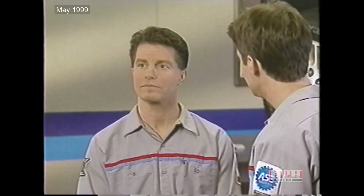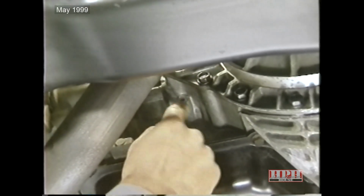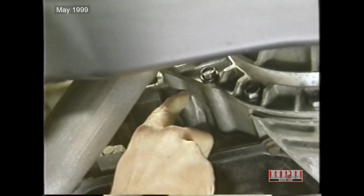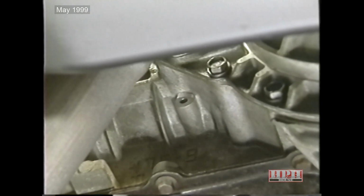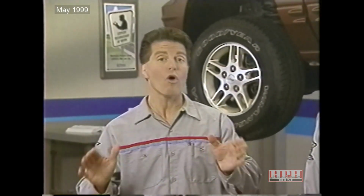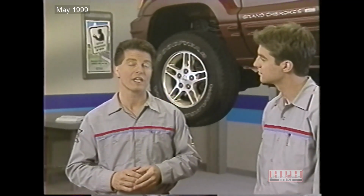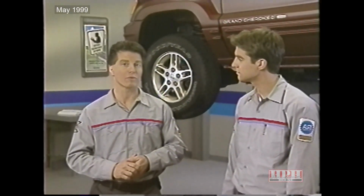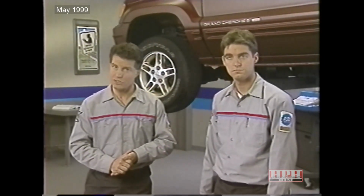Well, is that it? Almost. On vehicles with the 42LE transaxle, you'll need to inspect the weep hole for oil, which indicates that the transfer shaft seal for either the transmission or the differential is leaking. If oil is present at the weep hole, the transaxle will have to be removed and the faulty transfer shaft seal replaced. You'll want to refer to the appropriate service procedures to do this.